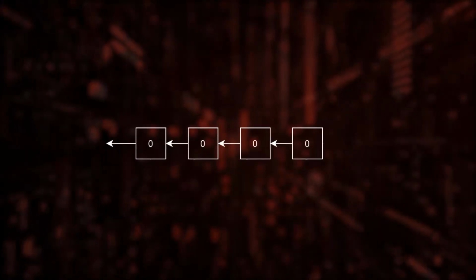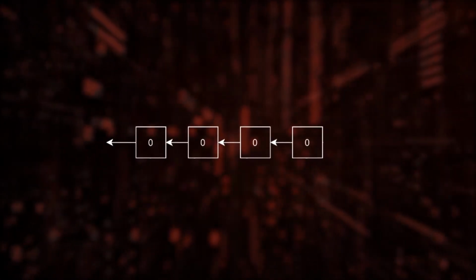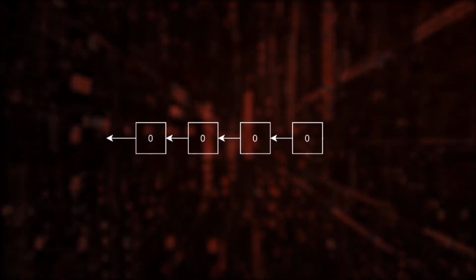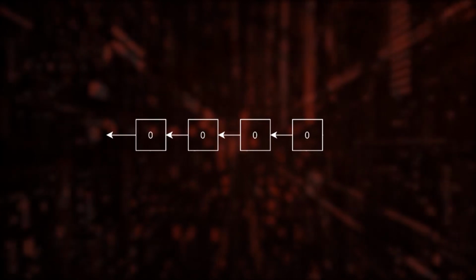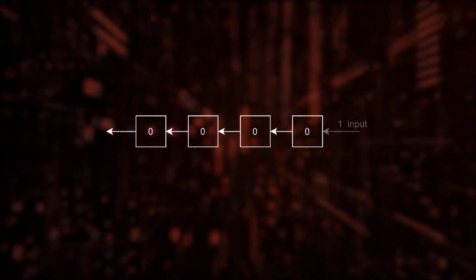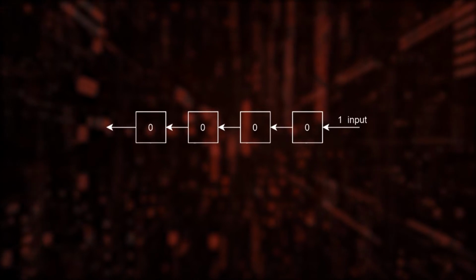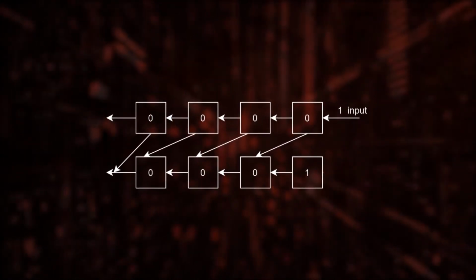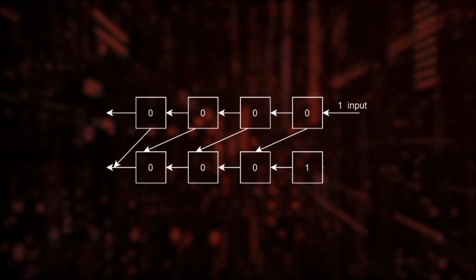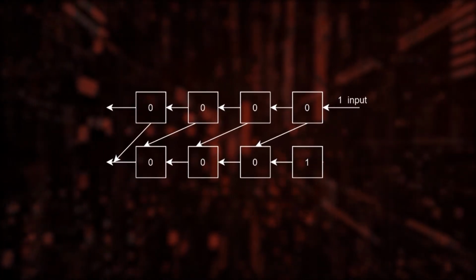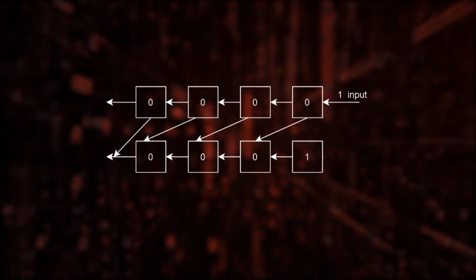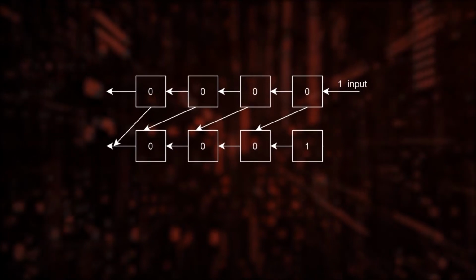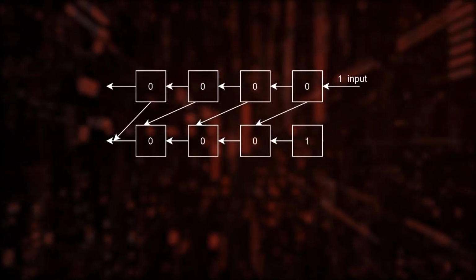Consider a 4-bit register. As given in the diagram, initially the register content is 0, 0, 0, 0, that is Q equal to 0. Now, you have an input 1. Then in the shift left register, the word becomes 0, 0, 0, 1. What happened exactly? The stored bits moved one position to the left, which caused the leftmost 0 to be dropped and the rightmost bit to be empty.